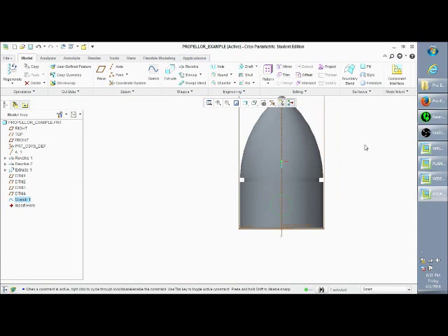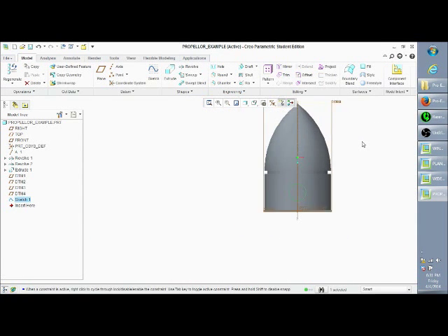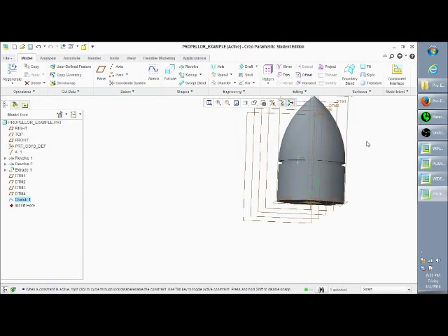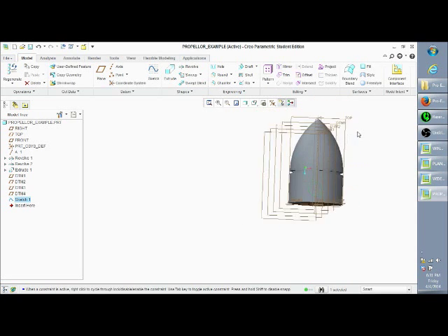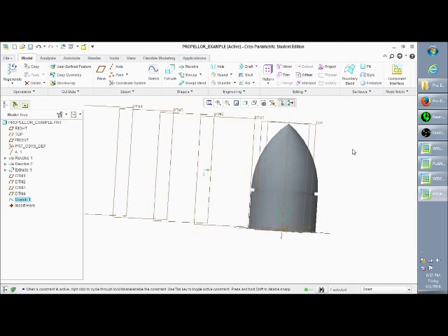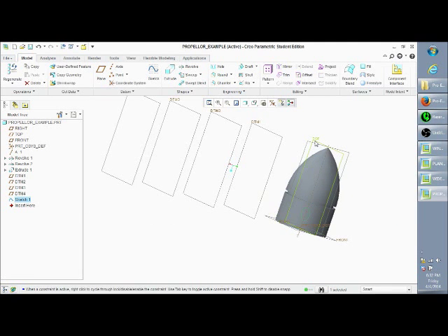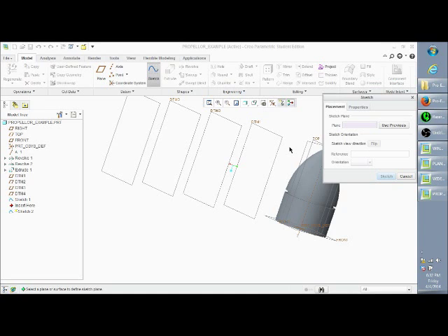And notice that they're not asking you to go directly into creating an extrude or a protrusion like I did in the revolve tool and stuff like that, because we're just creating a sketch for now, which really doesn't do anything besides putting a pre-made shape on a datum. So we want to go ahead and create, and now we want to start inserting our airfoils onto one of these datum planes.